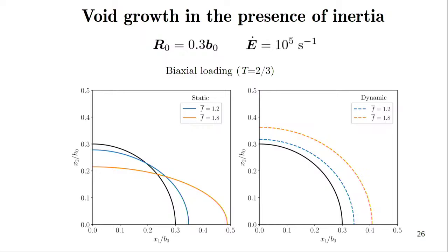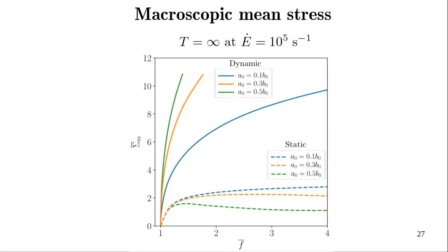So this is the effect of inertia, which is trying to expand the void in a more spheroidal manner. Now this is at the highest triaxiality, which is kind of a hydrostatic loading. Okay, so the highest triaxiality, highest loading rate.